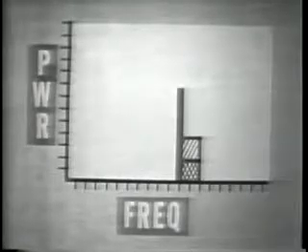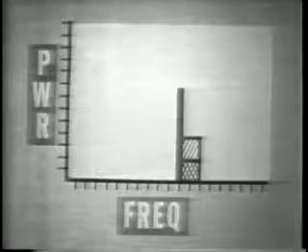If we eliminate one sideband, we would narrow the required frequency spectrum by 1/2. And we'd still have the same intelligence in the remaining sideband. And by putting the power from the removed sideband into the remaining sideband, total sideband power is restored and is contained in just one of the sidebands.